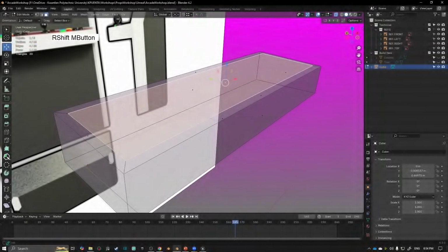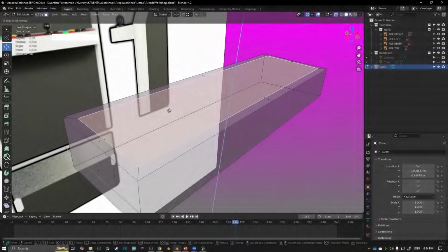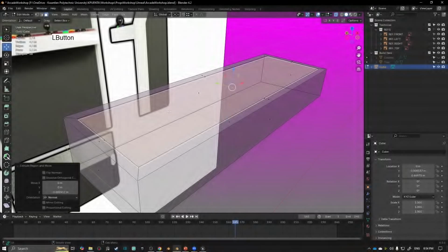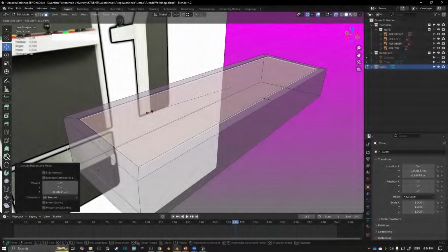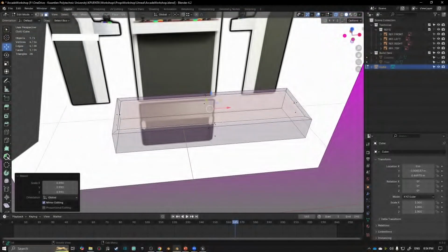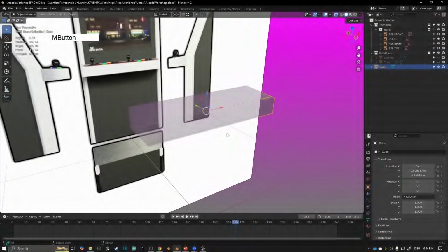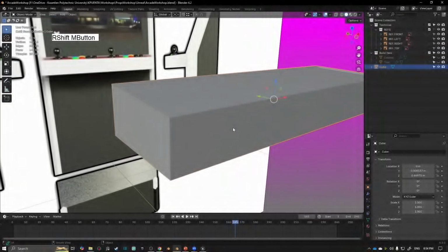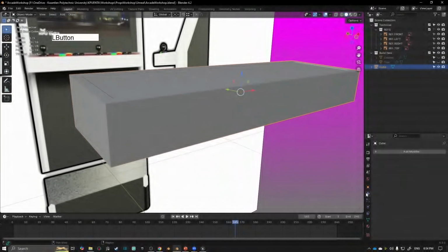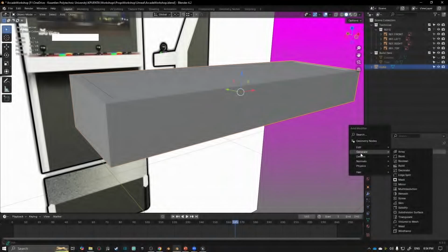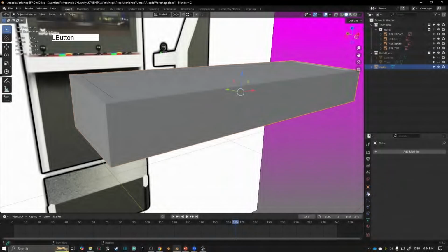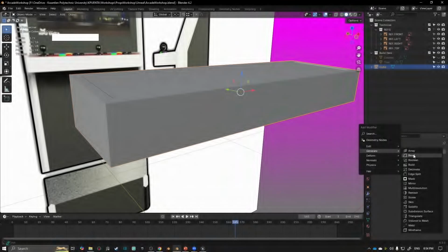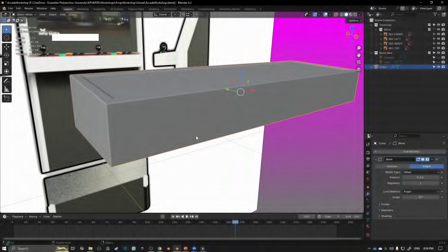Again, if you wanted to, you could extrude it down ever so slightly, scale it ever so slightly, it doesn't really matter. Okay. Now, if we want our stuff to look a little nicer, these really hard, nasty edges are not super awesome. I'm going to click on Generate under our modifiers, so this little wrench over here, and I'm going to put a bevel on everything.